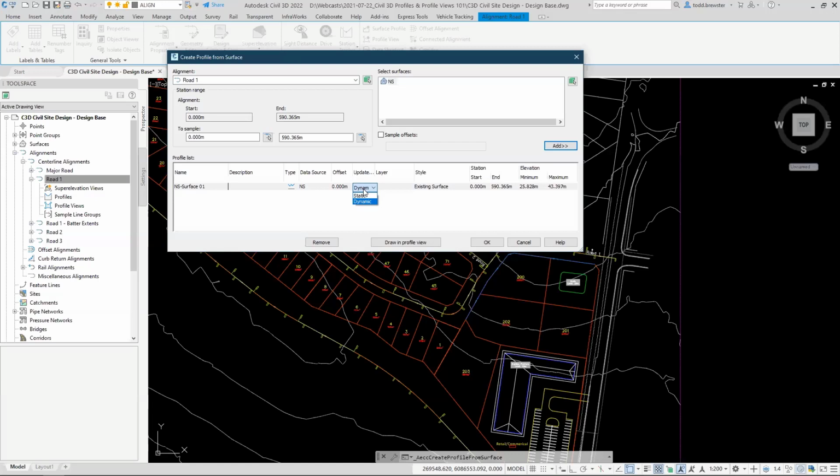If you bind that information into your surface, if it's on dynamic, then the long section will automatically update with that information. If it's on static, it's essentially a once-off extraction, and then you get like a freeze, I guess, probably a good way to describe it. The surface data will be basically locked to what it was at the point of extraction. You can flip it to automatic or dynamic whenever you choose. You can get into the properties of it and just turn it back on.